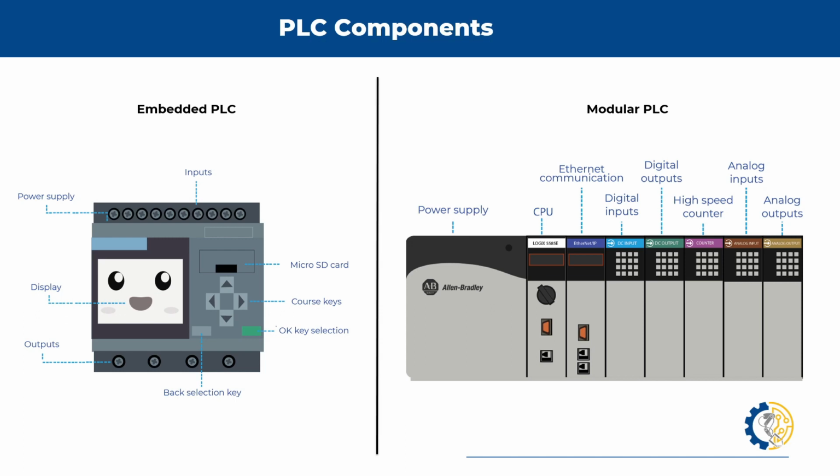So this is where we need to be very careful. Remember that for our outputs, it is recommended that we send DC signals, unless we have relays for AC that can support our PLC for that type of configuration, especially if they're relay outputs. Okay? Now we're going to explain this further down the line.